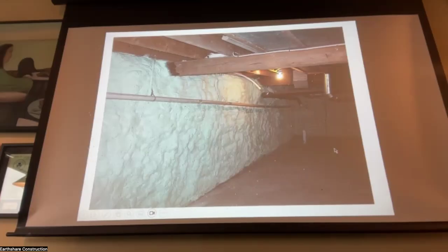Henri, my question is, you spray the top 3-4 feet of foundation wall, so you're getting below frost level? No, at 3-4 feet of the stone, no, this only goes to a foot, or this one doesn't, but I'll show you some too. So how far would you recommend the foam going down a rubble foundation wall? One foot below grade. Okay, so the frost is able to get into that wall from the outside. Well, you're not protecting the wall from the heat that goes into the wall from there down. Yes.